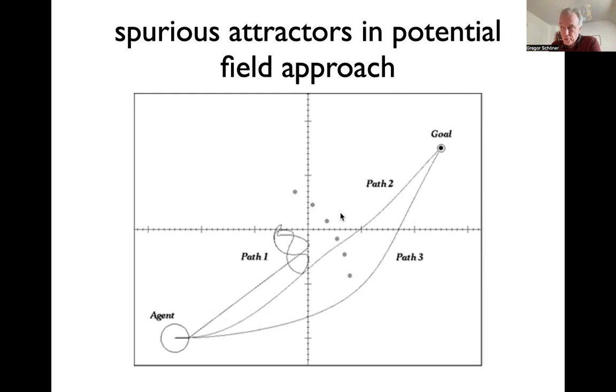There is actually a solution to that. And that's a solution we proposed in our initial paper, which is really to reduce the representation of the obstacles. That is, which obstacles are you going to take into account, to reduce that so that you only take essential ones into account. You could say the only essential ones are the ones that you're close to. So when you're moving in here, you're going to no longer take into account all these other obstacles and that one. You're only going to take into account these two. And that's what you design to have the right bifurcation so that you're not driving through those two.